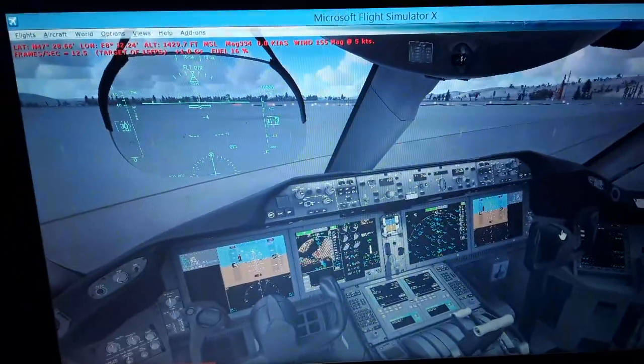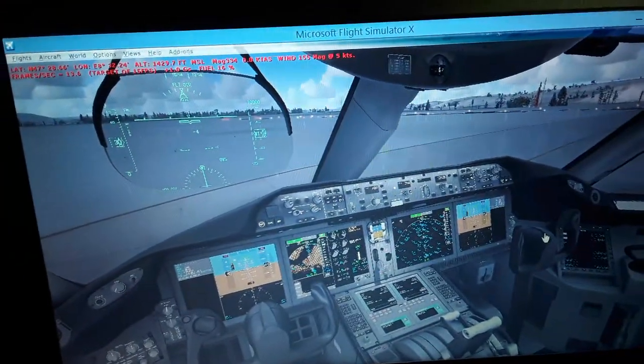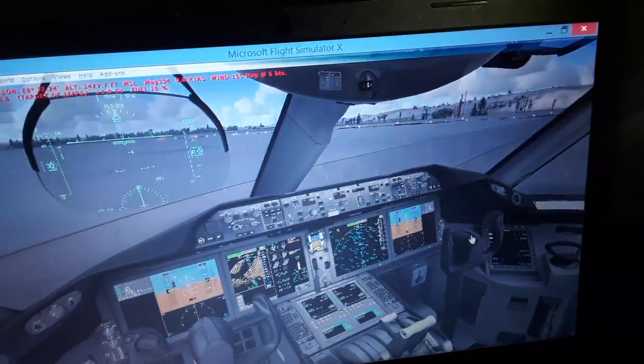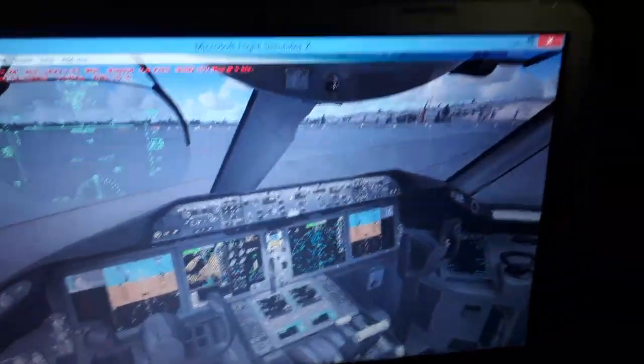So you can see the lakes, rivers, and the sea also in blue, and also in the terrain map we have the magnetic north pole and the geographic north pole and magnetic variation depending on where we are in the world. You can also see in the terrain map the airports displayed in blue with a 4-letter ICAO name. It's our own airport. You can see the runways you're going to use both for takeoff and for landing. Also we have the runway length, the runway heading, and also the taxiways using the GPS receiver.